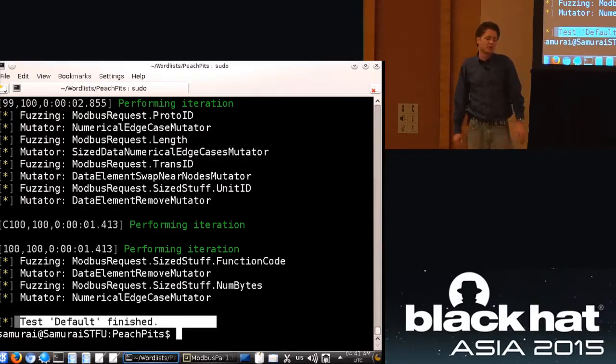What we recommend is that if control engineers need to get to corporate email, they have a corporate machine to do that, and to work in the control network, they have a control machine to do that. And so we have a very, very tight perimeter between control and corporate. Inside of the control network, you want to have multiple different perimeters as well. So defense in depth, keeping the attackers away. That's the first thing we do.